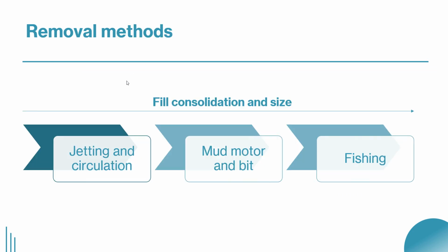The removal methods in general can include jetting and circulation. This is for the least consolidation and size of fill. And as the consolidation and size of fill increases, we can use mud motor and bit, milling operation, or if it has the highest consolidation and size, we can use fishing operation.